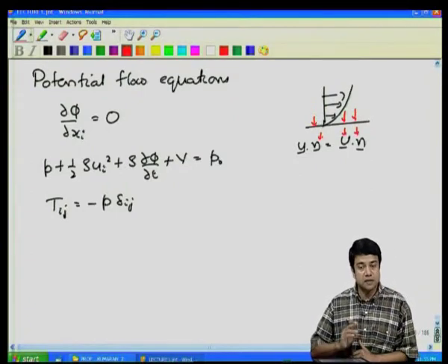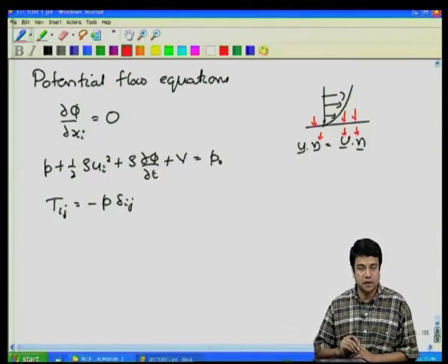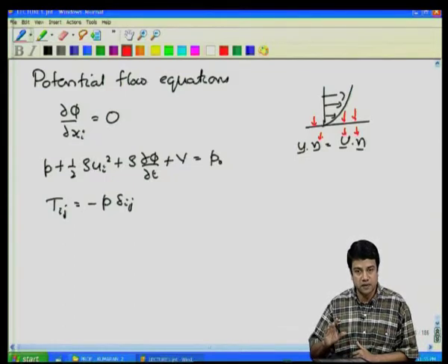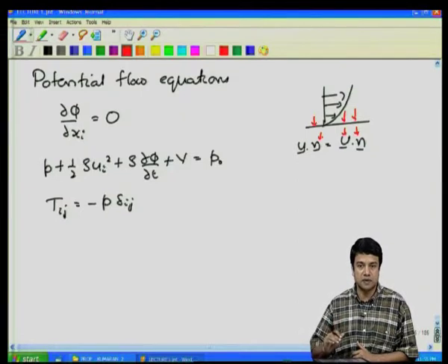As far as the tangential velocity boundary condition is concerned, since we neglected viscous stresses, there will be a velocity slip at the surface in the case of potential flows. The tangential velocity in a potential flow will not decrease to 0 at the surface. The reason is that we do not have the mechanism for reducing the velocity, the diffusion of momentum due to shear stresses.